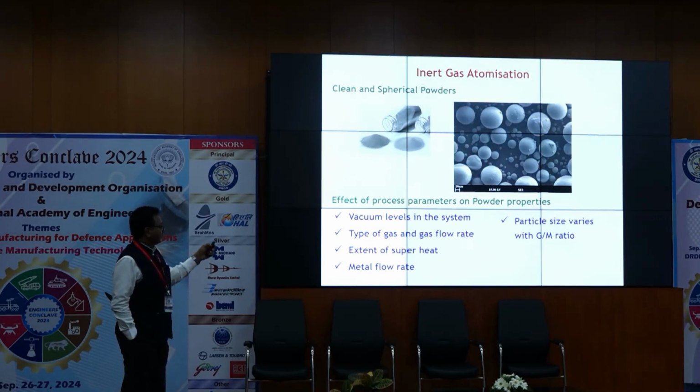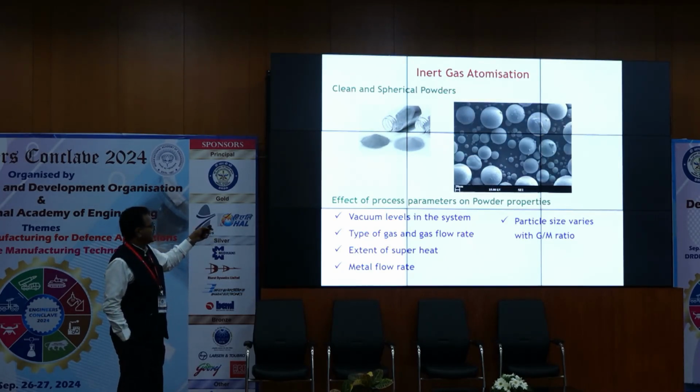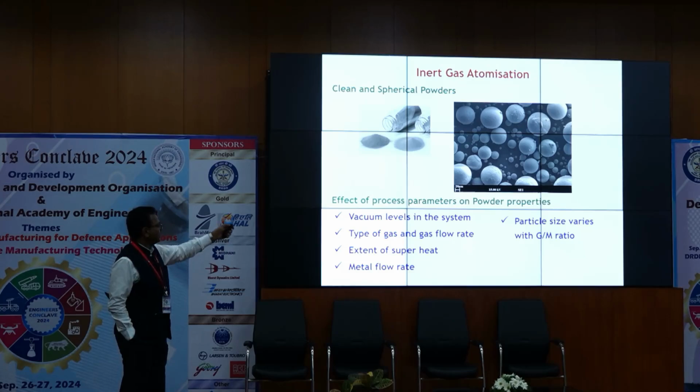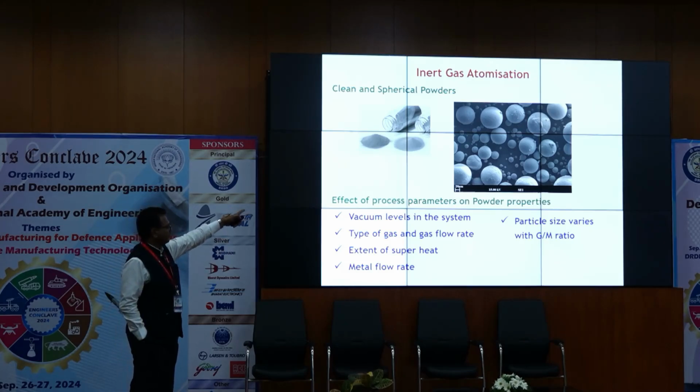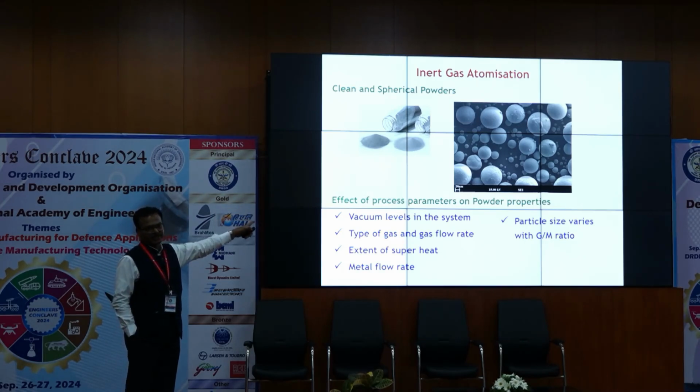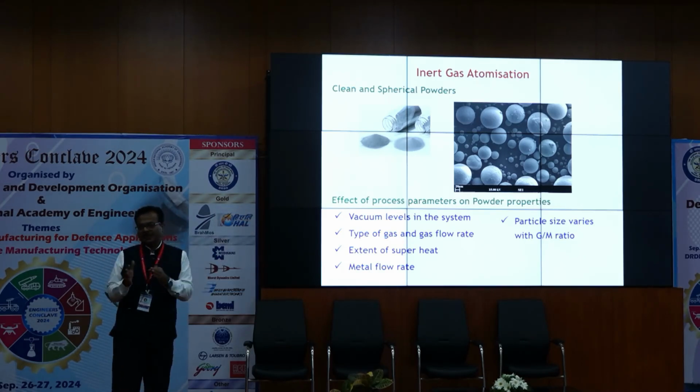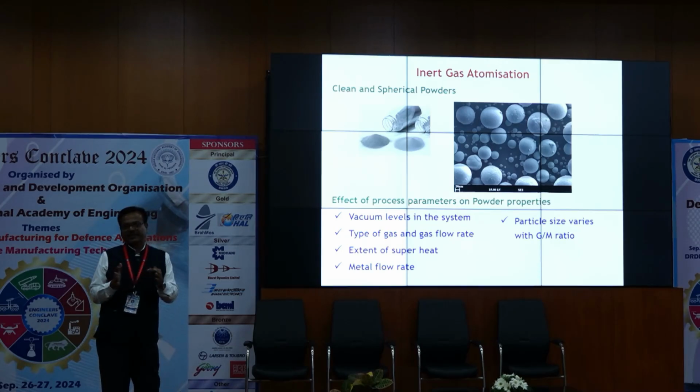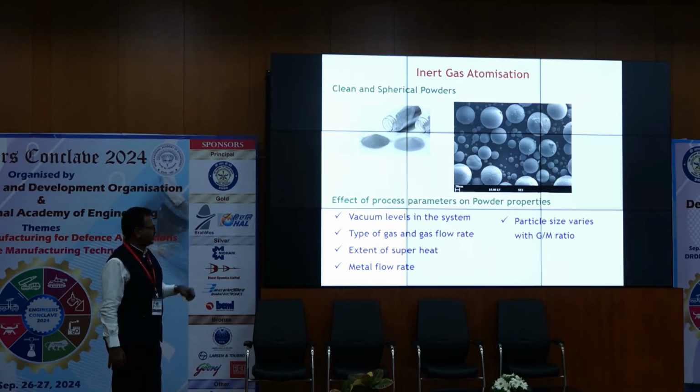Then, what I wanted to go through is the inert gas particle process. Ultimately, my aim is to get very good shaped spherical particles, with as few satellite particles as possible, and a uniform, very narrow particle size distribution. But that is very challenging.